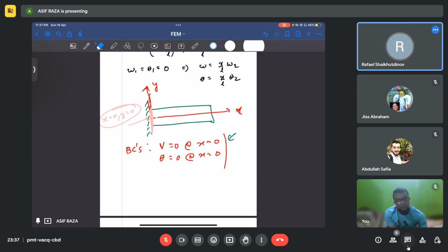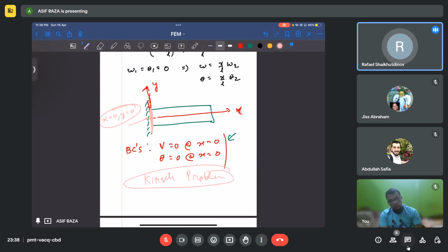I add them both and differentiate with respect to the coordinates, like epsilon x is equal to du/dx, and epsilon y is equal to minus Poisson's ratio multiplied by sigma x divided by Young's modulus. And I also take the shear stress definition. I integrate everything, and after integration,